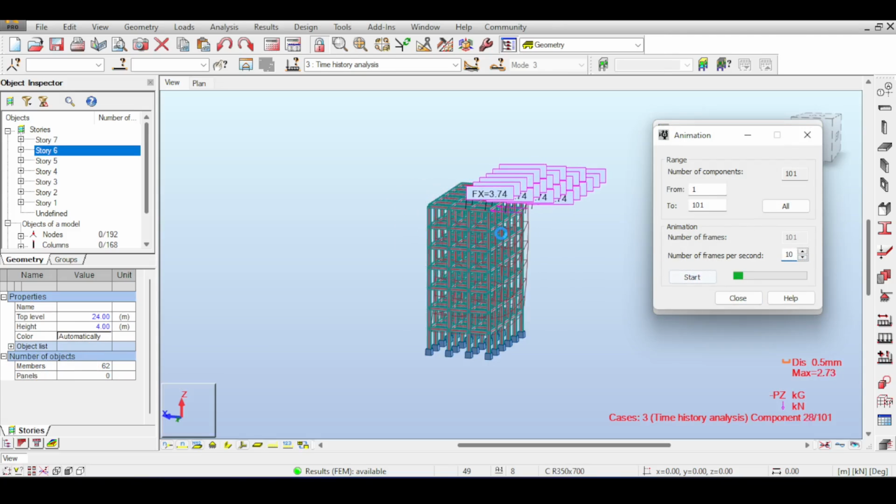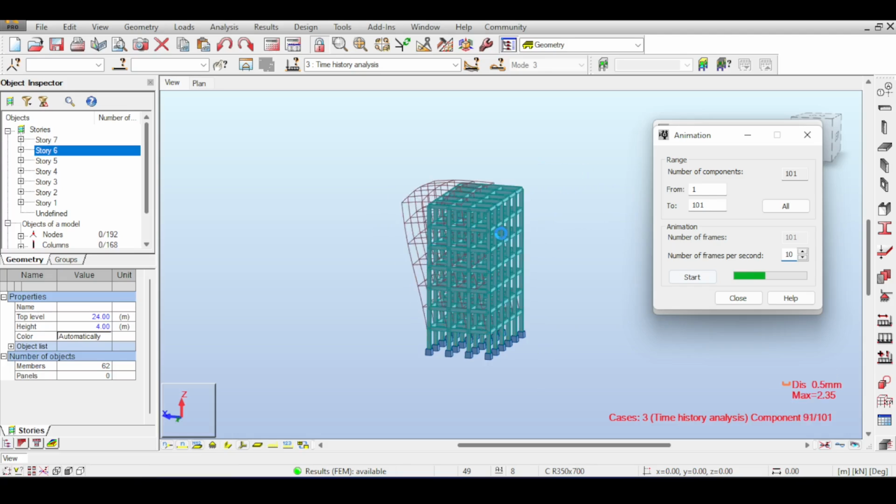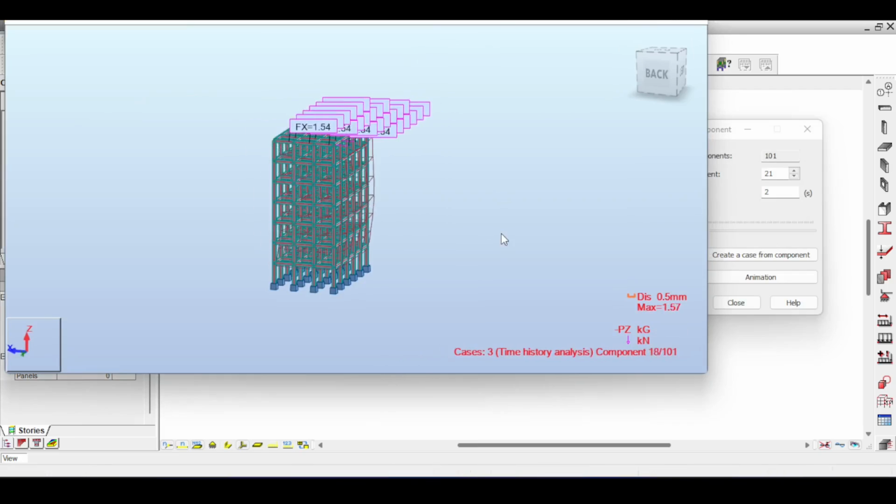Now, of course, you can see that the structure vibrates much more violently because the frequency is higher. You see, the more stiffness you have, the faster you vibrate, and because the structure has a strong stiffness, it's vibrating immensely. Don't be put off by this strange yo-yo movement. Notice that we are talking about 5 millimeters.